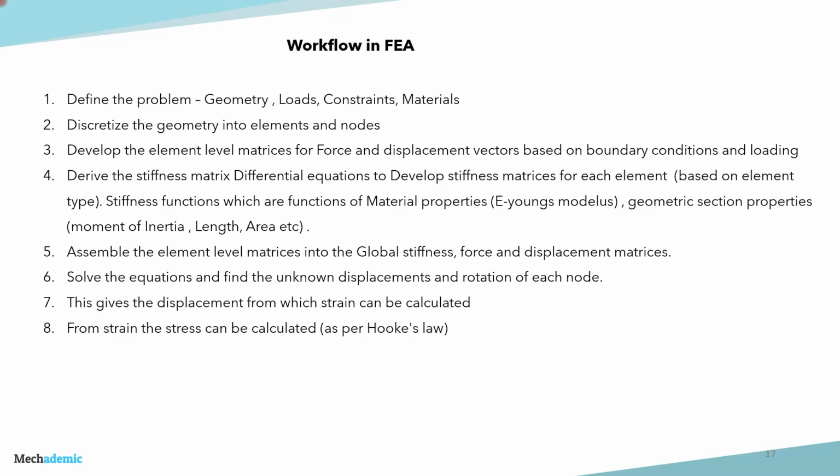And then we need to specify where the loads will be applied on that bracket. So what are the areas on which the loads will be applied? What will be the types of loads? And will there be any separate load cases, that is vertical load in one case, horizontal load in another case, or combined loads? So the load cases have to be known.